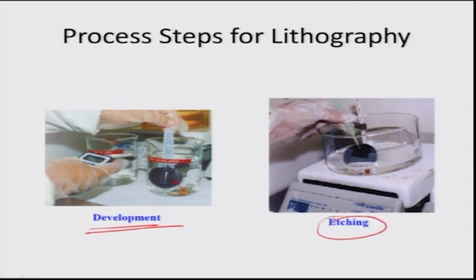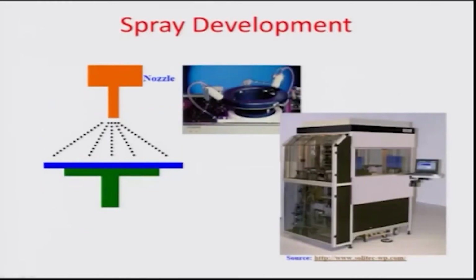Use that as an etch window and further etch the wafer surface, so that you could have features imprinted on different regions. On a high throughput machine, you can do the same by spraying developer solution and by having multiple wafers stacked up and doing this process in an automated manner, more on projection lithography,